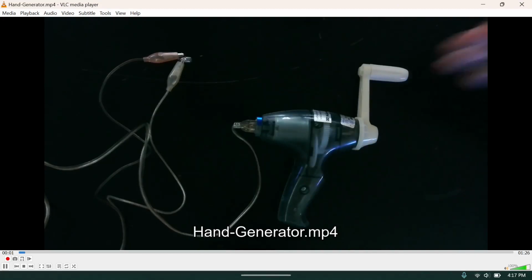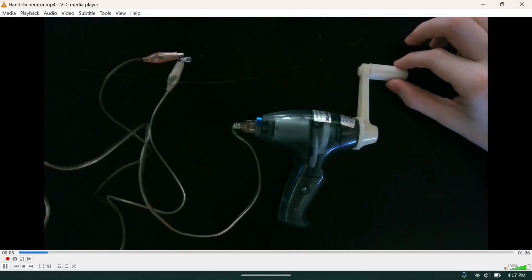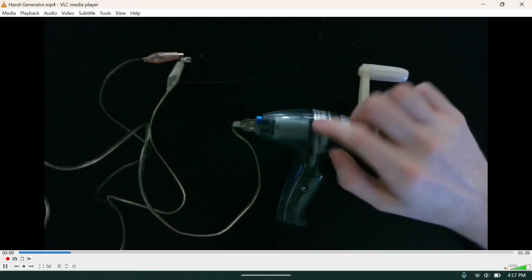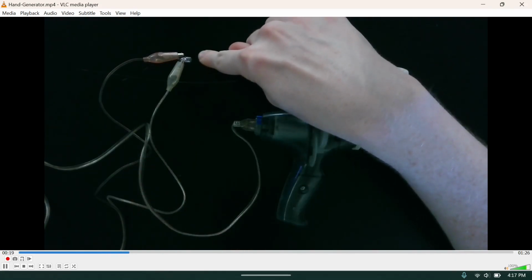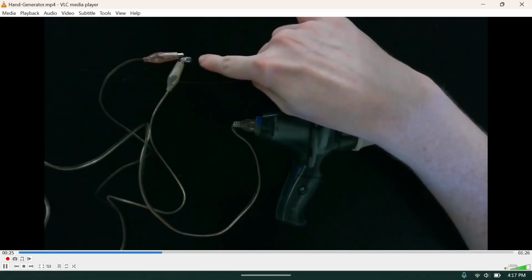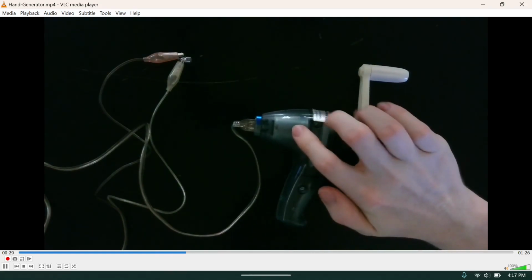Okay, so this is a little hand crank generator, and if I turn the crank on it, it is going to rotate a coil inside of this metal enclosure. There's also a magnet in there, and so as the coil rotates in that magnetic field, that is going to induce a current that will flow through the wires and light up this little bulb right here. So the mechanical energy I'm going to be producing with my hand is being converted to electrical energy that flows to the bulb through the use of a magnetic field.